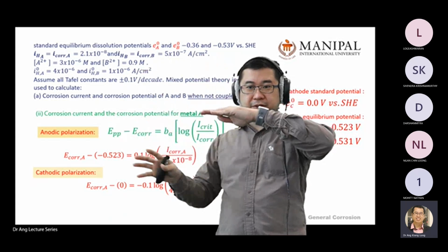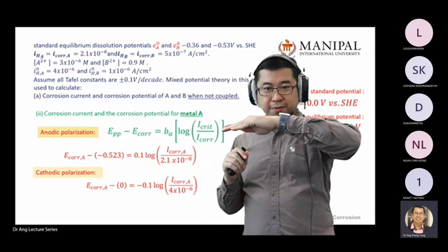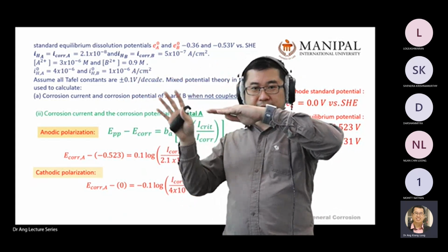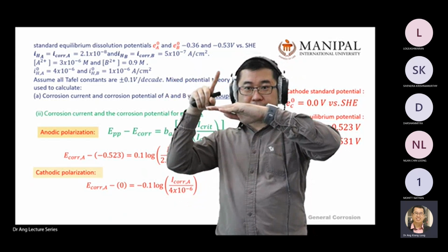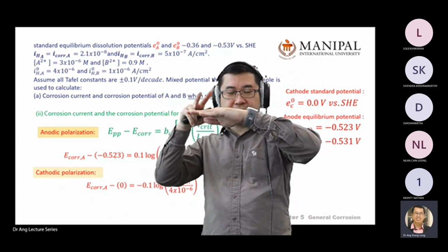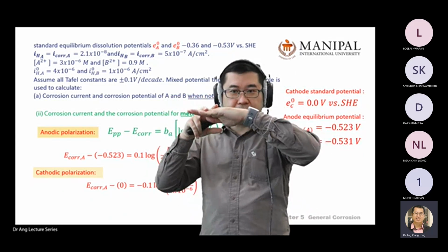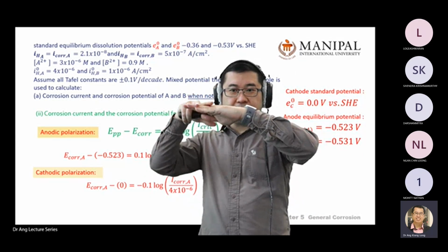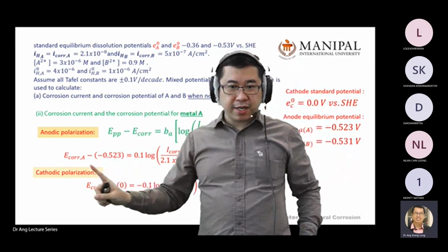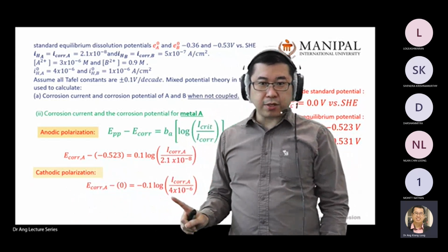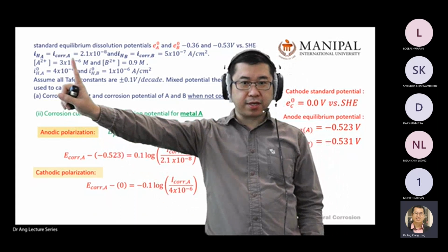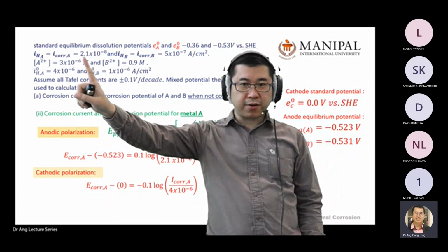Attract positive charge around it. In this case, we assume acidic. So when acidic, H positive charge will be attracted to the cathode, right? So here you have hydrogen created on the high nobility metal, and the hydrogen evolution happens on the surface here. So that's why for cathodic polarization, you are using the hydrogen evolution value here and not the corrosion value for I.